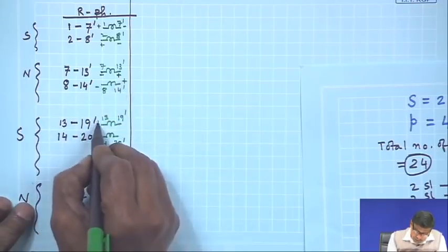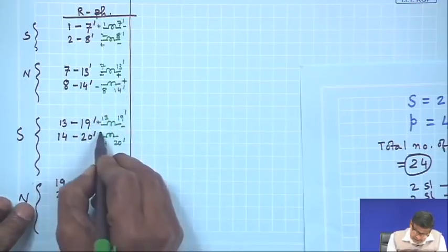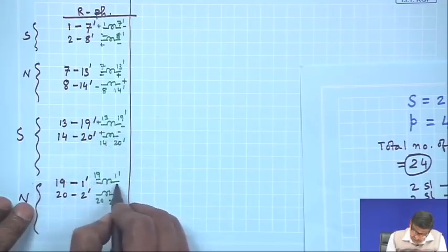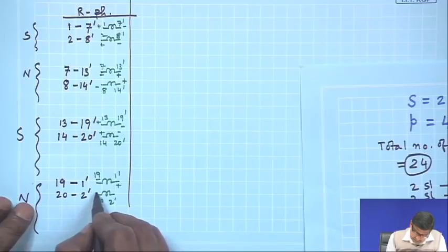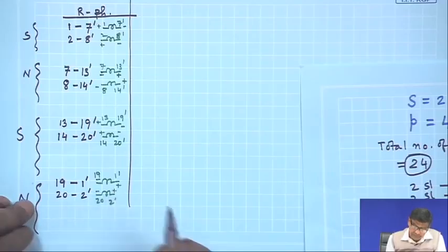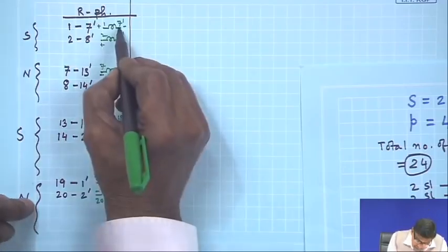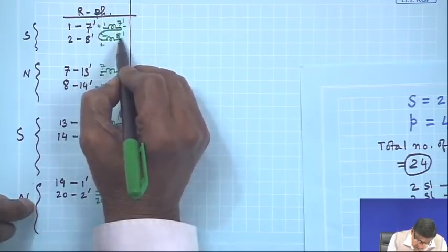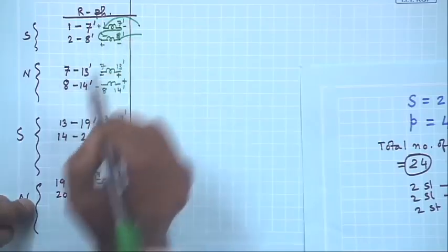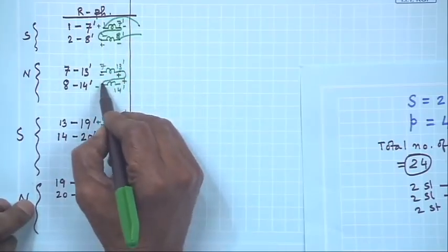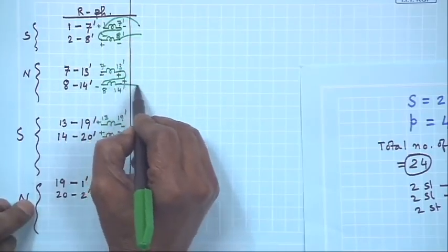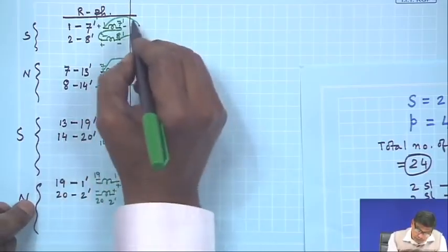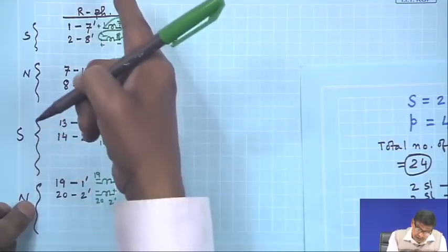So, under south pole whoever is it will be like this and under north pole it will be like this. And then you connect this in series and get these two terminals, connect them in series and get these two terminals. These 4 groups are there for R phase only,